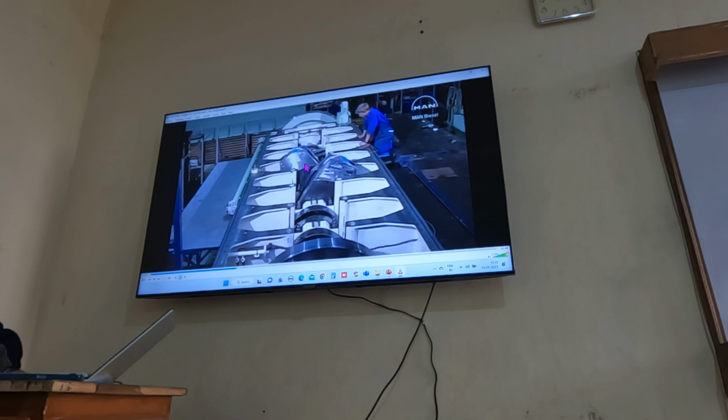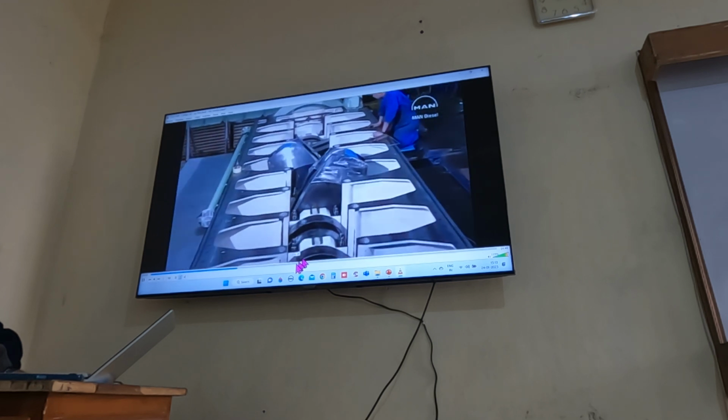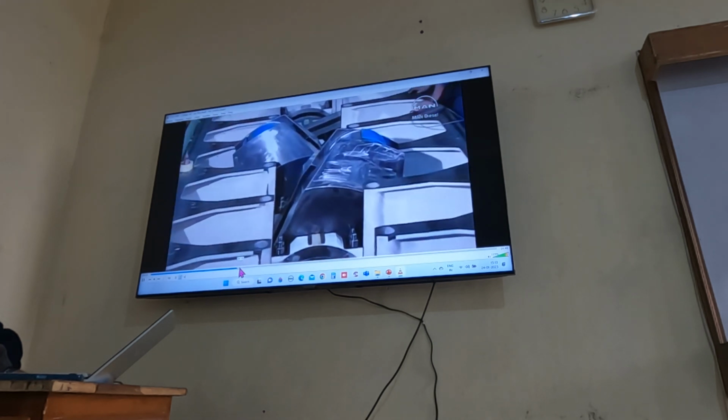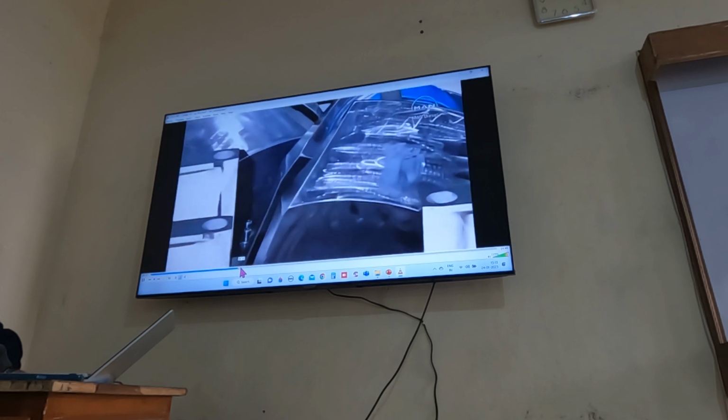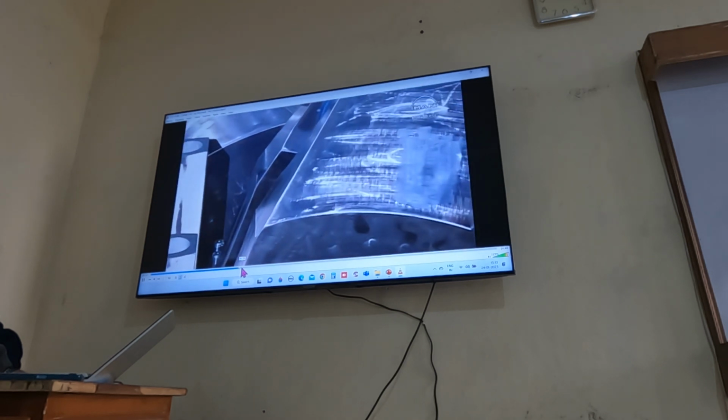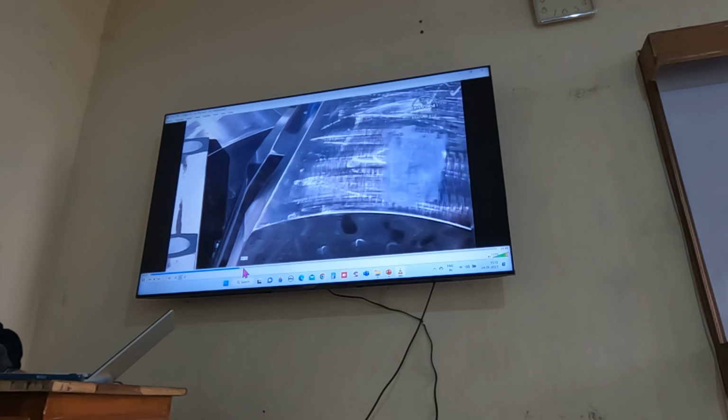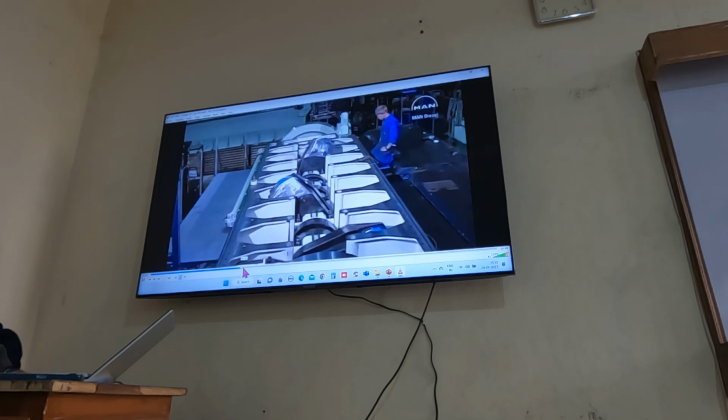On some engines, the crankshaft is so big that to facilitate manufacture and installation, it's made in two halves, which are later bolted together. Each half is built up from a number of main bearing journals, crank webs, and crank pins.